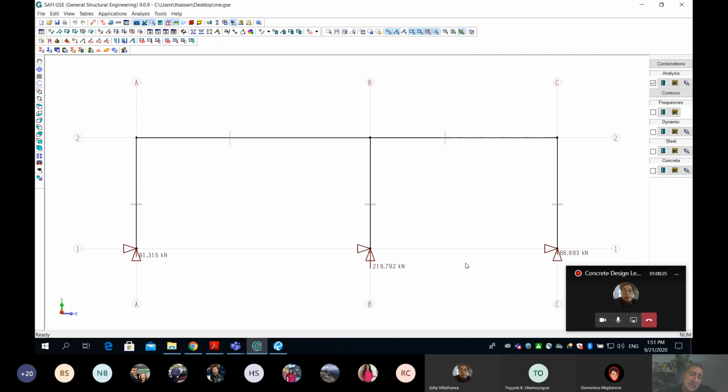If you change the sign, for example from -10, which is supposed to be going down, to +10, again it doesn't know. It will just trust you and give you the bending moment and the shear. As a designer, your responsibility is to do some visual checks to make sense of your model.